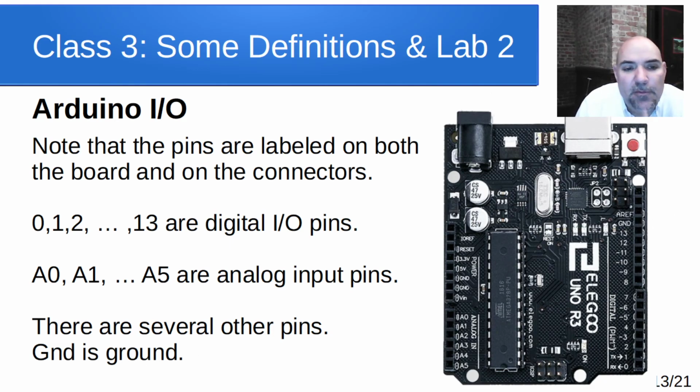And one other thing that was mentioned in the lab sheet was the LED. The LED is right there. These ones will turn on and off when you're programming it or when it's communicating. You'll see those flicker as it's communicating with the host PC. But there's also this one. That one's connected to general purpose I/O pin 13 right here, the one that's right next to where that LED is. And that LED will turn on or off based on whether the state of pin 13 is high, it'll turn this on, or low, it'll turn that off.